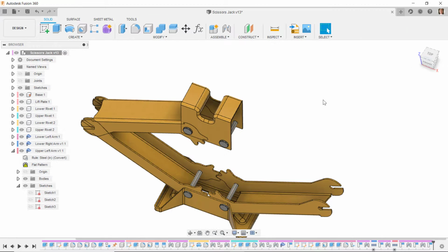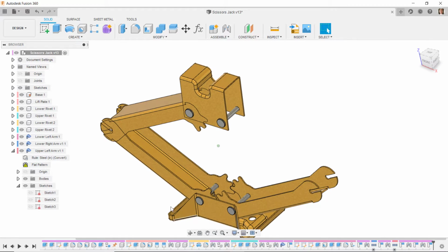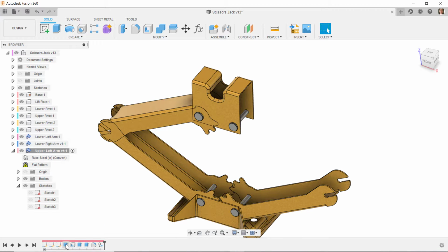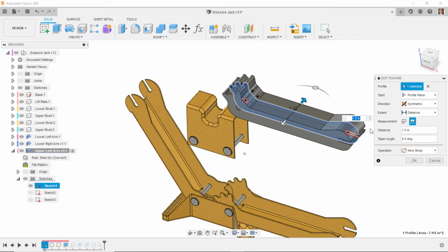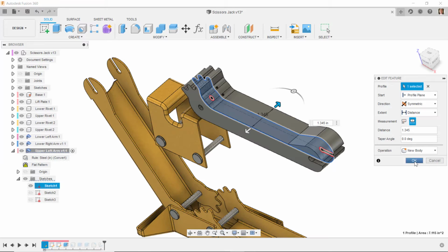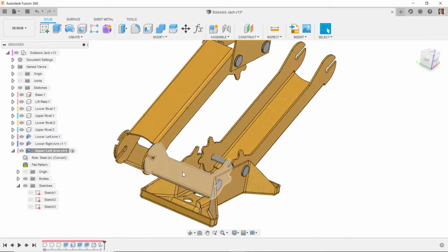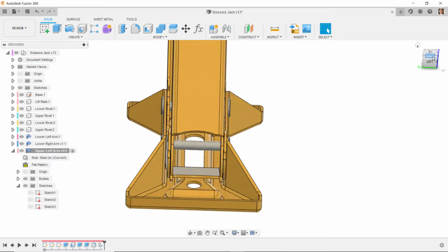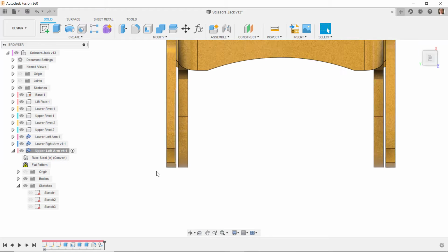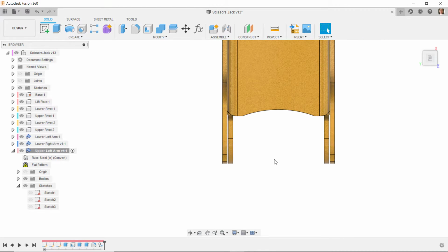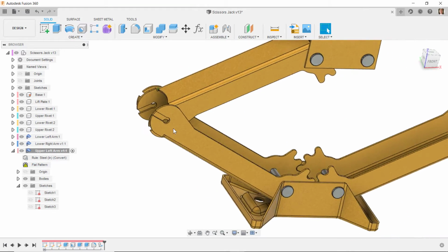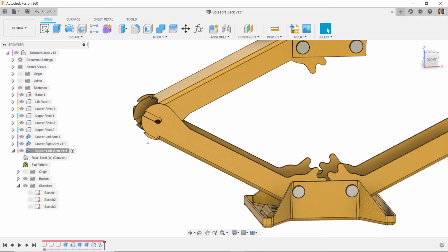We'll say okay to that, and then I need to change the extrusion thickness. So let's go to make this component active, and I will change the original extrusion distance, and I need for that distance to be that 1.345. We'll say okay to that. And so now this component is inside of this component. Notice that there is a little bit of clearance allowed from here to here, from here to here. So design clearances into your mechanism as you go. Don't wait till it gets out to the shop floor and assume that somebody's going to fix it after it gets to the shop floor.